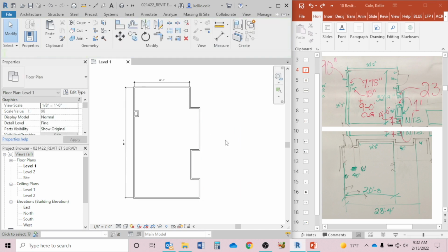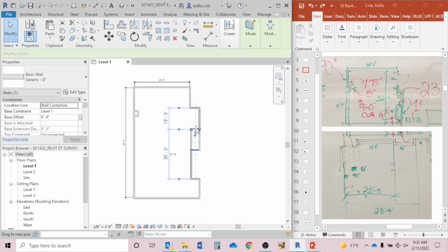If I select things in the opposite manner, like touching right, dragging lower left, it grabs everything that the rectangle touches, right? Compared to just what's in the rectangle if I do it in the opposite way. Why don't you take a minute? You can touch a wall, move it in, touch another wall, just drag. I'm just holding down the cursor, right?